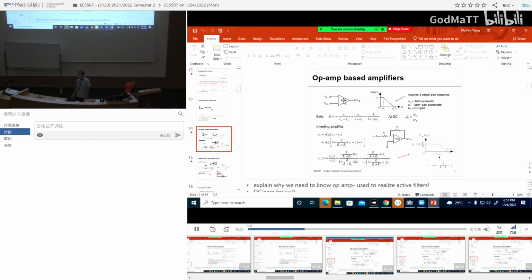So that was the other great invention, feedback. That's why we come up with an op-amp based amplifier. That means we use the op-amp, but we use it inside a negative feedback loop. So here is your op-amp. Two inputs, a transfer function or gain function in the Laplace domain, one output. So this is a simple open loop transfer function of the op-amp.